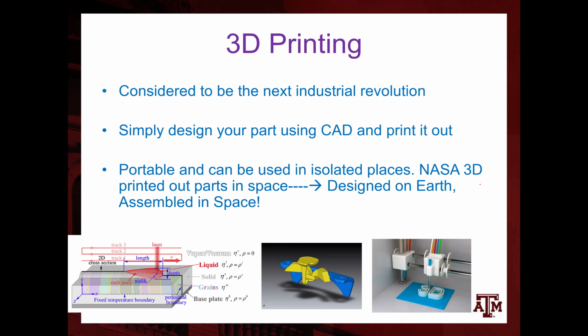So there are different types of additive manufacturing and 3D printing, but one relatively straightforward example to think of is, for the case of printing metals, where we are using a powder and a laser to melt those powder layer by layer, and then we deposit this layer by layer until we have a specific 3D structure that we can design using CAD or AutoCAD.